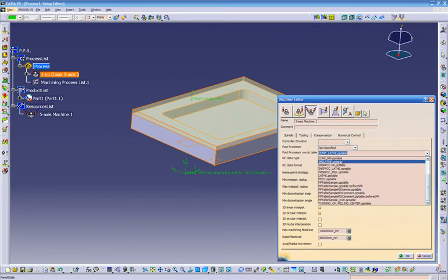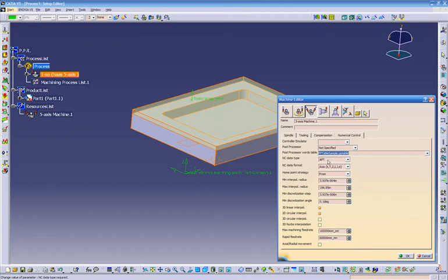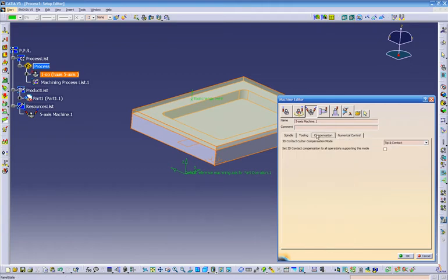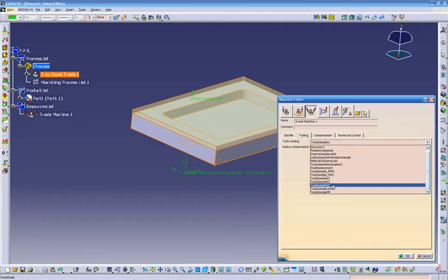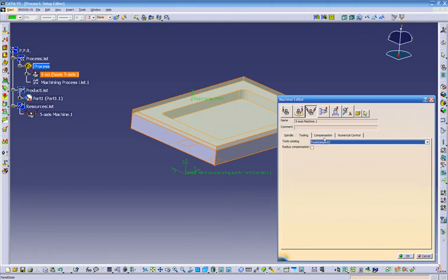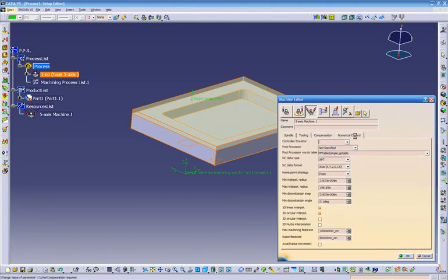I also have my own PP table for APT source because it's pretty easy, but if you feel comfortable, this always works the best. APT is the sample. So we're going to leave it as a sample for now, and that's the only thing we change over here. This is the spindle home position, but the only thing we change is the tools. We have to pick up our library and cutter compensation and the sample of your post processor.